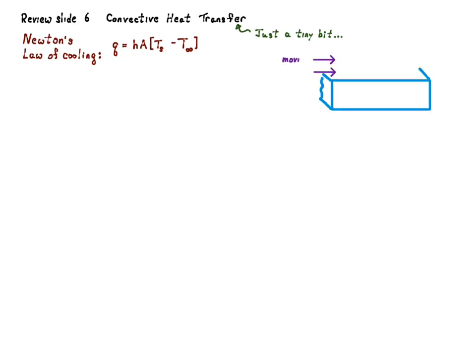And how we're going to define these is by defining a solid substance given by the blue box here, and we're going to have a fluid flowing over it at a velocity u infinity and a temperature T infinity. And how we're defining these infinity terms is that this is the temperature and velocity that the free stream has beyond the influence of the solid substance. The solid substance will consider having a surface temperature of Ts, and the heat rate is going to be the heat that's moving from the solid surface into the fluid, and we're going to call this convective heat transfer.